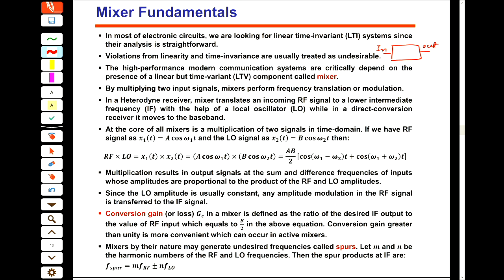These are the 2 conditions that we have. I mean that if a system is linear and time invariant, it cannot generate output elements which are not available in the input. So this system should be, for example, LTV or nonlinear, if we want the frequency of output and input to be different, or a combination of the input frequency and some other frequencies. This is what we already mentioned.